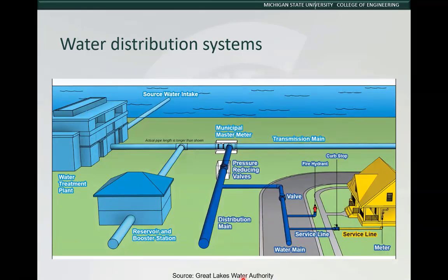So I've shown this slide before, but again, I really want to reiterate what we're looking at in terms of these distribution systems. And we've talked about the distribution as a whole, what we're focused on is right here, what is referred to as the service line, typically what is public. This is your curb stop. That's where the shutoff is. As part of the lab, or assignment 3, you should have actually gone out and looked for that brass plate where the shutoff is. And then this is the private side. And the gooseneck would be right in here.